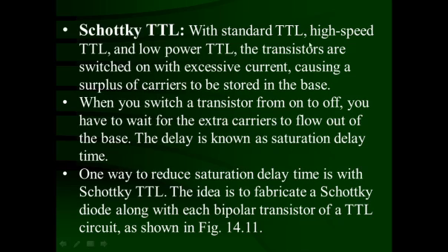With standard TTL, high speed TTL and low power TTL, transistors are switched on with excessive current, causing a surplus of the carrier to be stored in the base. When you switch a transistor from on to off, you have to wait for the extra carriers to flow out of the base. The delay is known as saturation delay time.